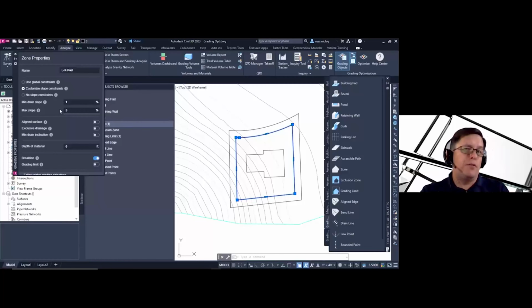Now I'm actually aiming for 3%. Again, I'm opening up that parameter envelope to let it find where this should be. I'm expecting most of the triangles will end up at 1 just by the location of it in the middle of that grading limits.